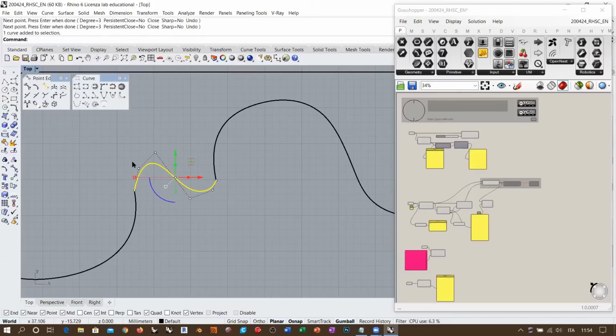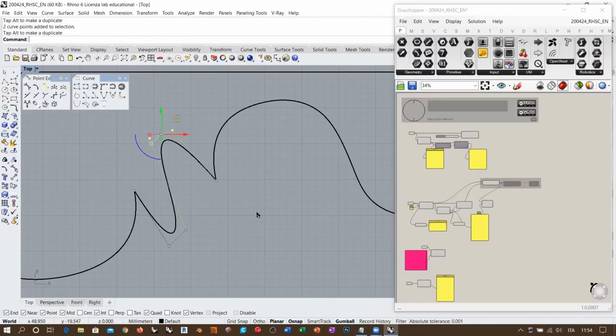By drawing this, no matter where I place the other control point, it's absolutely irrelevant, okay? But I have the right topological structure in order for Rhino to edit the shape of this curve and create curvature continuity in this connection point and in this connection point. We will be discussing this later when we deal exactly with the continuity.